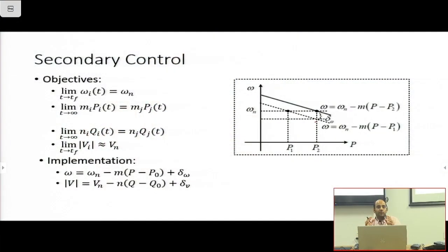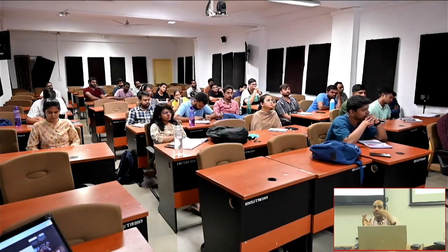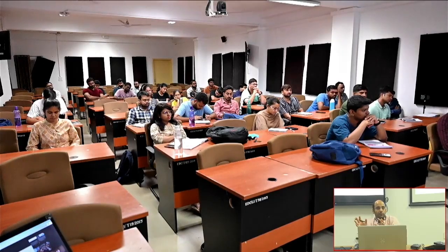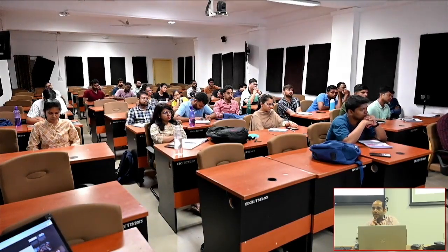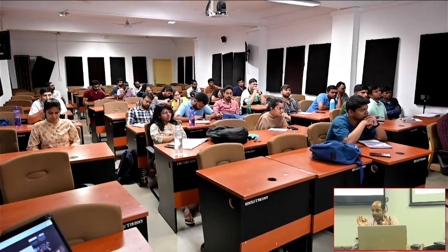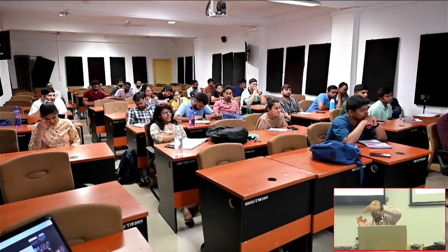What is that steady state? One second, two seconds, not saying. At steady state, mi pi equal to mj pj, for each source, however many there are in the microgrid: 1, 2, 3, 4, 5, 6, 7, 8, 9, 10. For everyone, mi pi should be equal to mj pj. Now, if mi equal to mj equal to m, meaning we are keeping the gain the same, m cancels out. What is left is pi equal to pj. That means for every i and j in the system, every ith and jth source will have the same power.